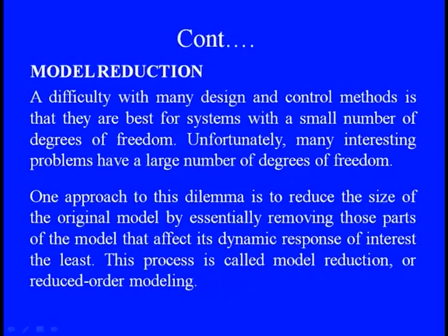One of the specific things is the modal reduction, because there is always a dilemma to reduce the size of the original model by essentially removing those parts of the model that do not affect the dynamic response of interest. When we reduce the model without affecting the dynamic response of the entire structure, this process is called modal reduction, or reducing the order of the entire system model.